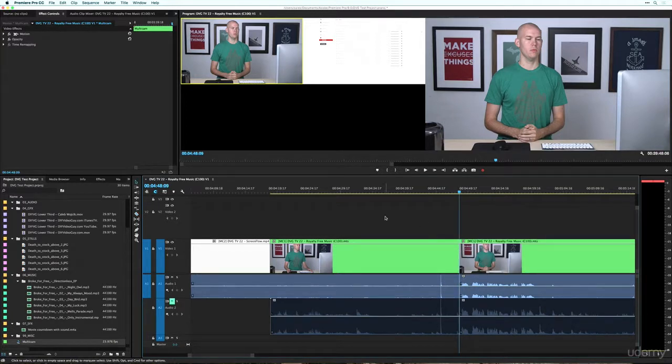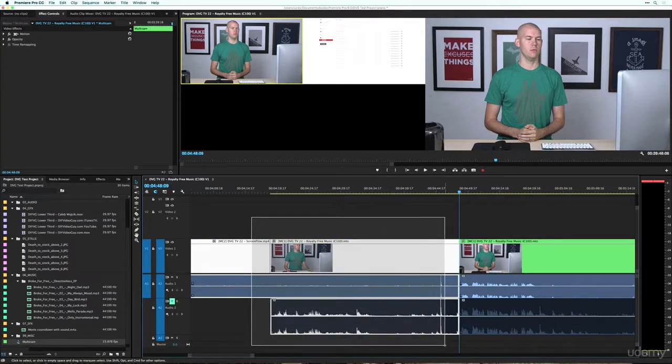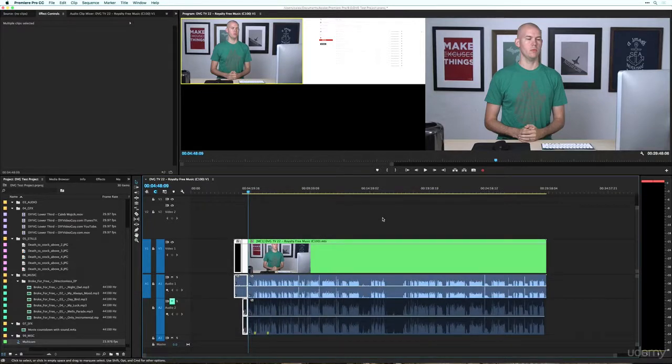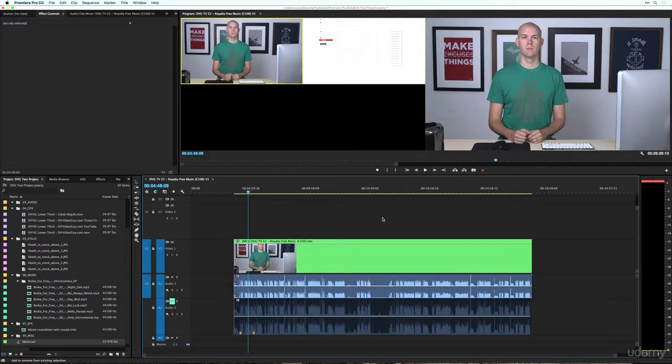I'm gonna click V to go back to the selection tool, select everything before that cut, and what I'm gonna do next is called a ripple delete. And a delete would just be, let's delete these things I have selected and leave everything else where it is. A ripple delete will make everything in front of that piece, and actually for you, it's gonna be this side, everything in front of that will ripple back as far back as it can go and as far back as you've selected. So if I go ahead and zoom out completely here, ripple delete for me is Shift Delete, and you can see that everything that I had selected went away and everything else shifted back to that point.